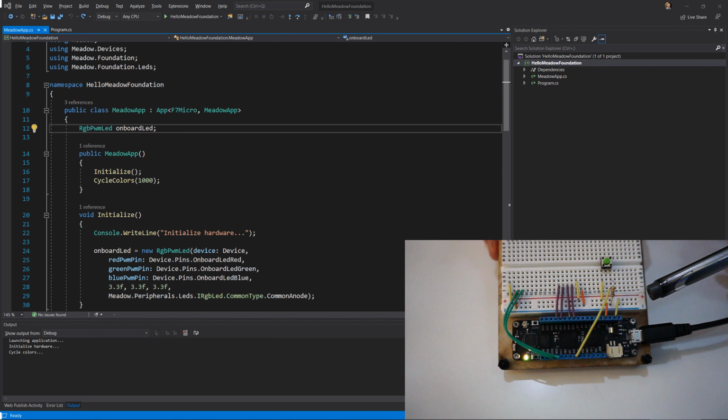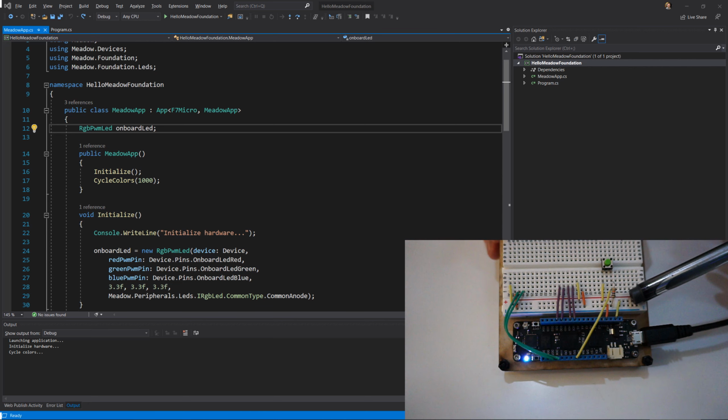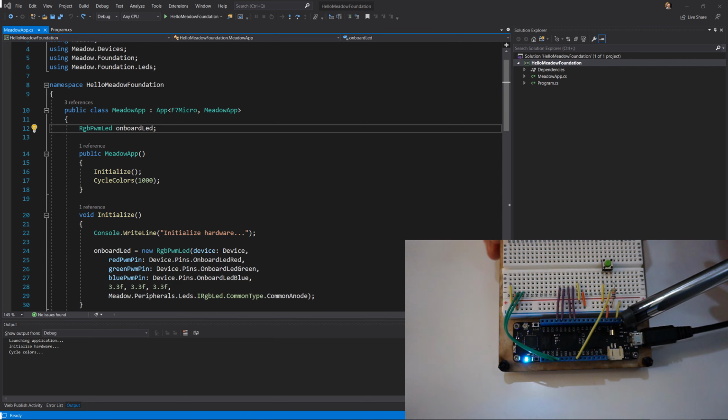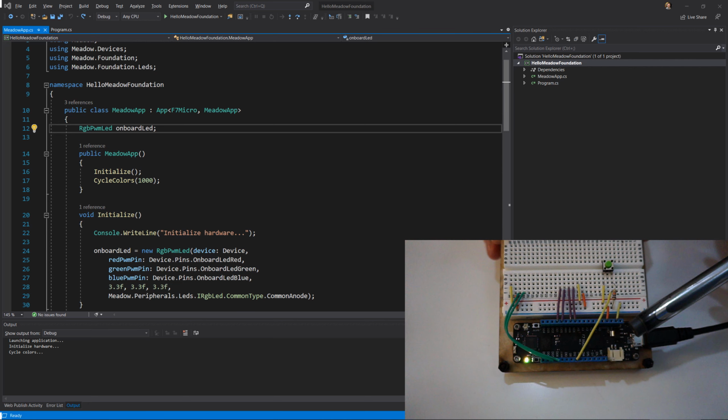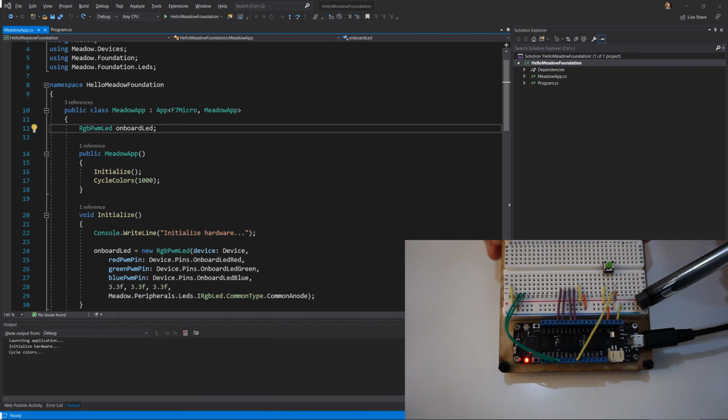So see what this red plus is? Well, all of the pins, all the holes across this row here are connected. So when this pin comes to the 3.3 volt rail or bus supply, it will power all of these pins. That gives us a power bus, a 3.3 bus.